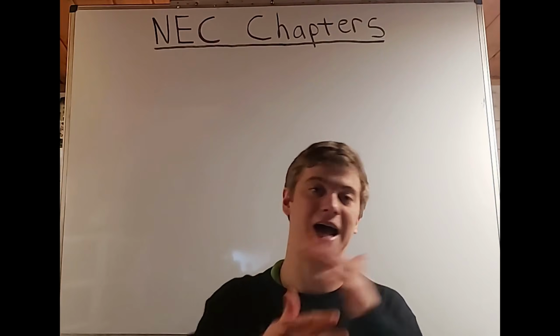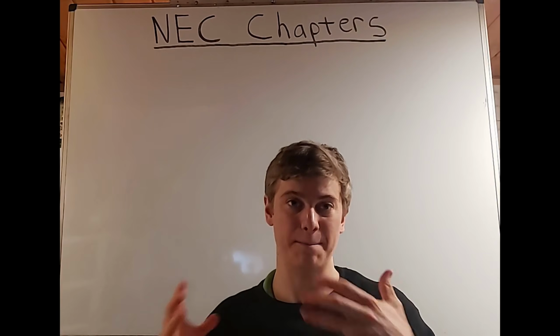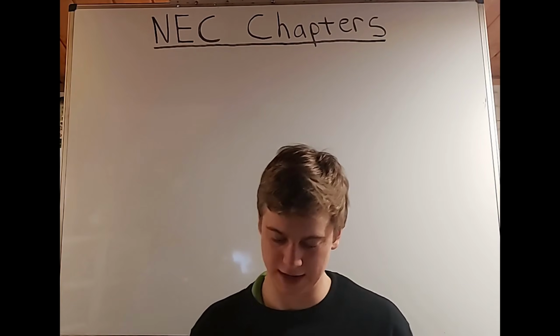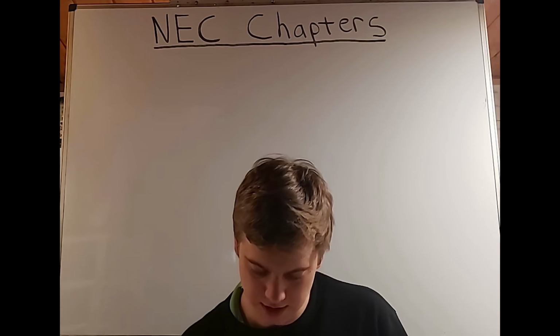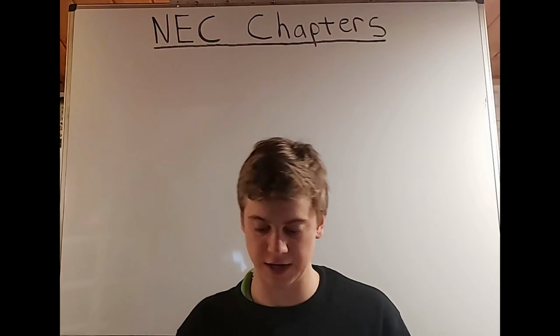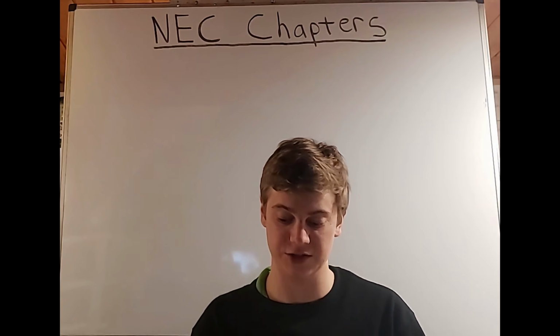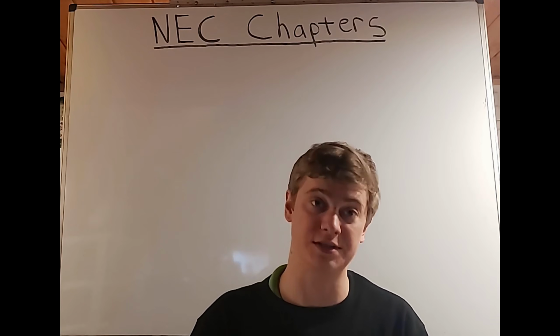Okay, so you want to have the equipment able to be cooled. It's not backed up against a wall. It doesn't have other equipment crammed right next to it. It's pretty straightforward and obvious, but now you know this is in the codebook. It furthermore talks about equipment that is designed for floor mounting, and it talks about clearance between the top surface and adjacent surfaces, and how it shall be provided to dissipate rising warm air.